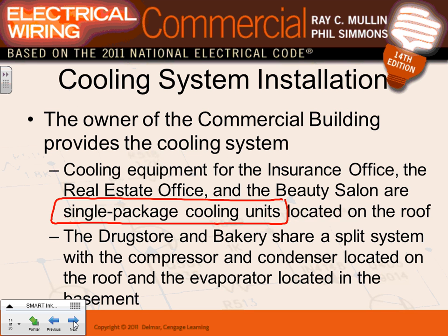The other type is split system. With a single package unit, you have one unit and everything is in that one unit. It's like window air conditioning. When you have window air conditioning, that's a single unit. A split unit is like the one in your house, right? You have the coil in the basement and the compressor outside. That's basically a split system versus single unit.